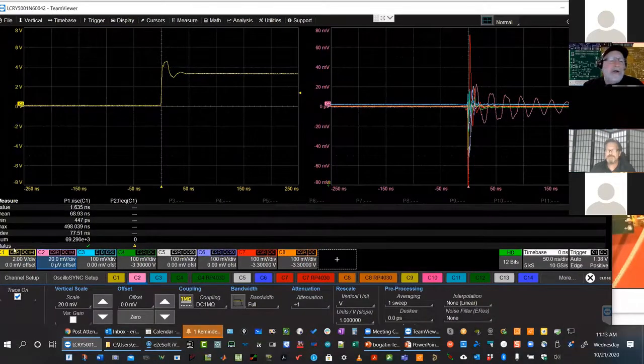In the scope, I have the scope set up for 1 meg input impedance. That's a recipe for ringing noise. I've got a low impedance from the driver, 50 ohm cable, 1 meg. Any fast edge that gets in there is going to be bouncing back and forth. We're going to get ringing. And how do you eliminate that? That's where 50 ohm termination comes in.